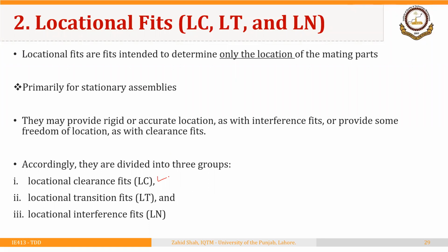So we are having locational clearance fits, we are having locational transition fits, and we are having locational interference fits. And we are focusing now on this first class, that is locational clearance fits. So they are also clearance fits just like RC fits.